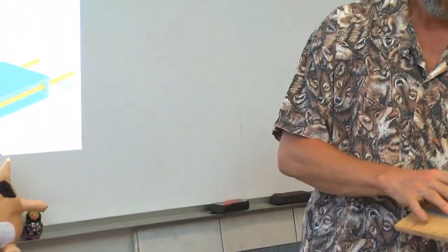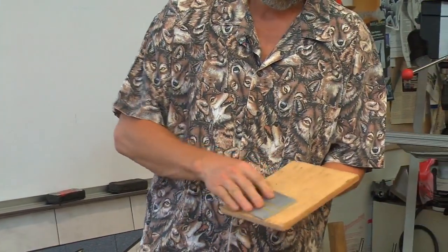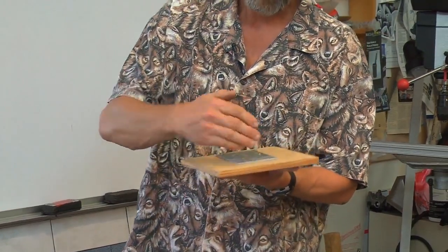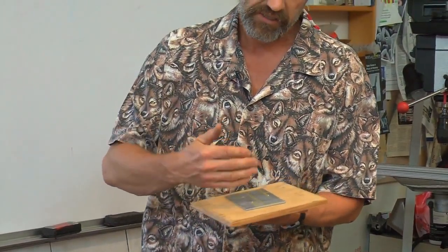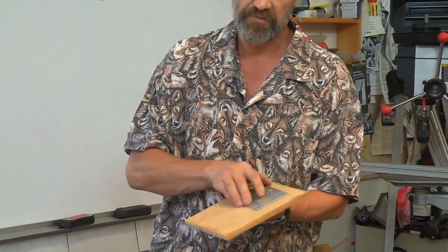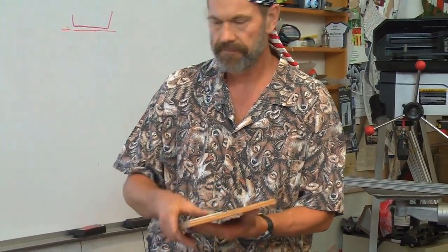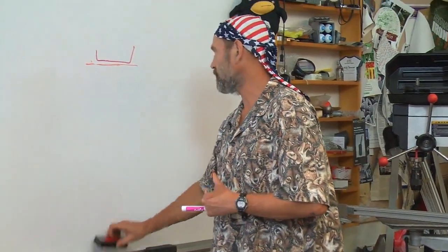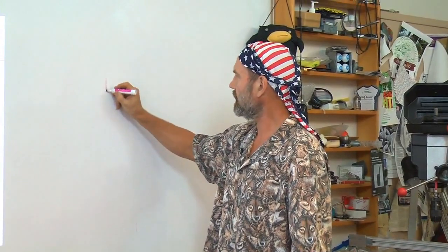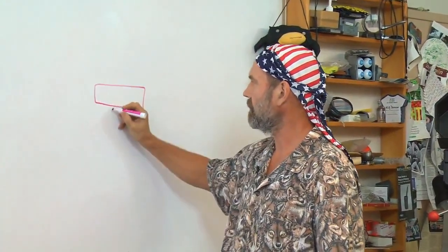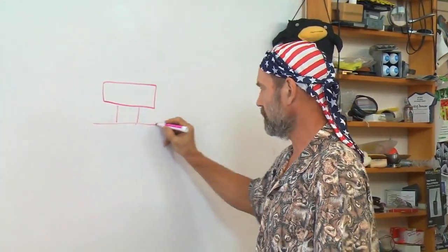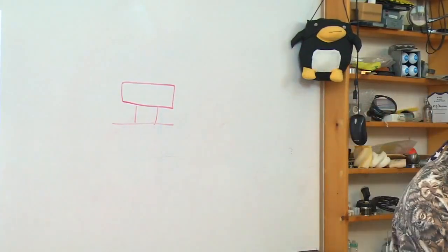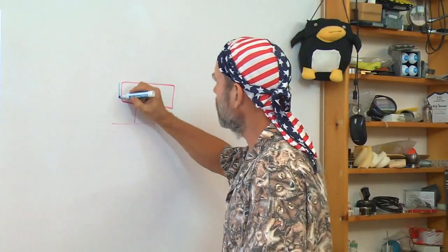But that flat on flat has only stiffness vertically. You have to put other features and hence other sliding contact bearing surfaces to provide the guided motion you want. There are many different geometries with which to do that. I can have a bearing rail, and this is called a boxway structure, with bearing pads.